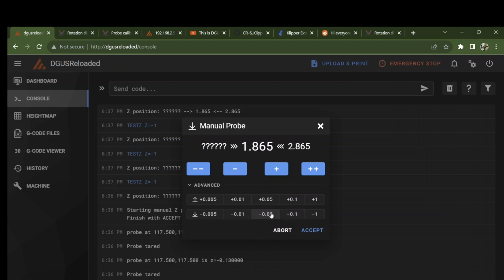And when I'm there, then I start using smaller increments until I can see no light between the nozzle tip and the bed surface, or I can see in a reflection, depending, if I'm using a glass bed or a wham-bam bed, maybe I can see a reflection of the nozzle and I see the nozzle kiss its reflection. Whatever technique you want to use, most people will shout back, paper method. So yes, you can use a piece of paper, lower this thing until it's scraping the paper, but now your nozzle is not at the bed, it's the thickness of the paper above the bed. So you really should make a measurement of the paper thickness and subtract that from the final value you got. But that's how you use Mainsail and Klipper to calibrate your Z offset.